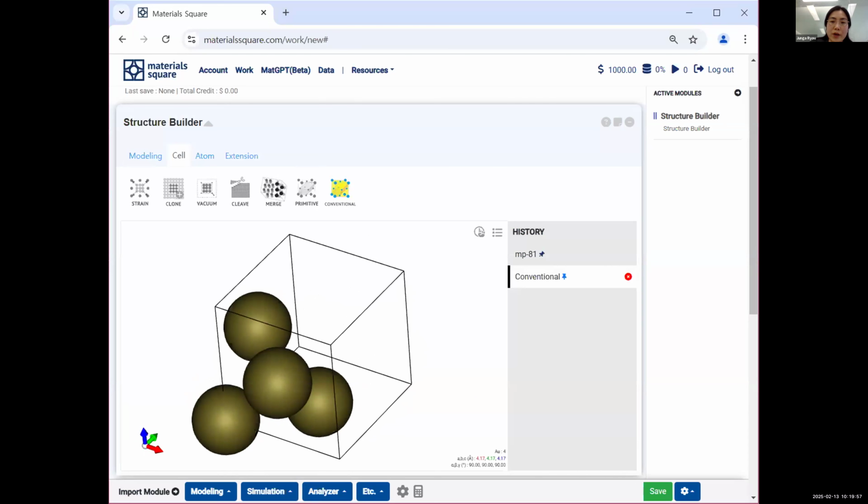Okay, here we can use Miller index to create a surface. However, it is important to note that we need to find the lattice constant of gold for the calculation, depending on the input parameter, before making the surface modeling. That means we need to run the VC-relax calculation first, find the lattice constant, and then use the Miller index. However, since our goal in this webinar is to only use the modeling tool, we will just skip this step.